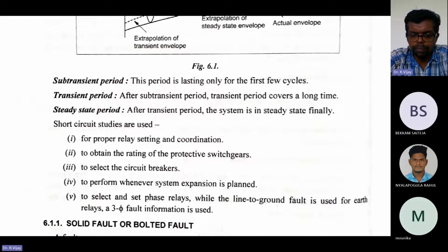Say for example, as a power system engineer, you need to plan for the long term. So if you plan for this much kVA load, or this much megawatt, say for example 0.25 megawatt of load in a particular substation, you may need to plan that substation for 0.5 megawatt or 1 megawatt load.